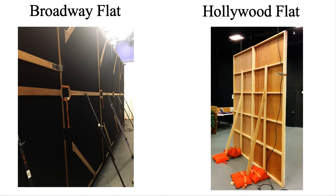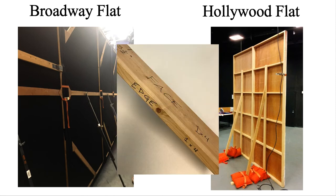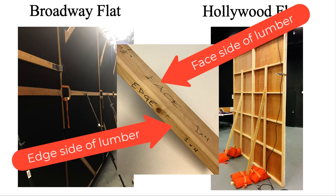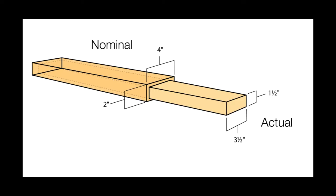The first thing you think of when you think of a set is probably the walls that we put up on stage. Those walls are made of panels that we call flats. There's a design called a Broadway flat, and that's when the construction is built on the face of the wood. And then there's also what's known as a Hollywood flat. Those are a little bit more structural, and the 1x4 is laid on edge to construct those.